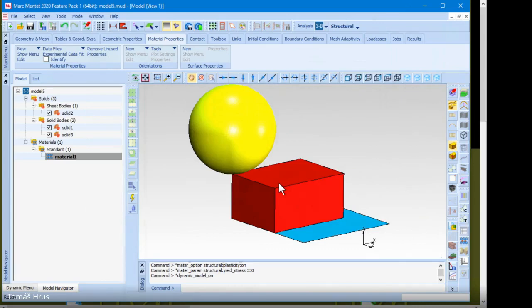Because we are now in space, the mesh will be a little bit greater. That means there is a large number of nodes, and because the displacements of nodes are the unknown values of the problem, if we are in space, the problem is bigger from the mathematical point of view, because there are many unknown values and the system of equations is greater.